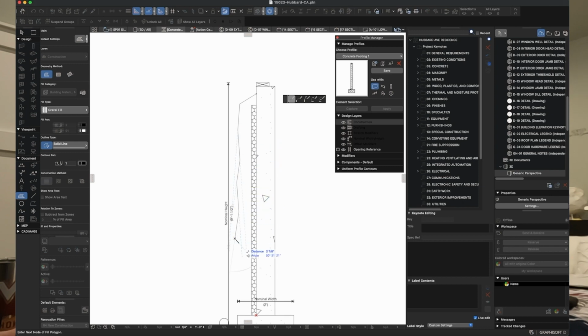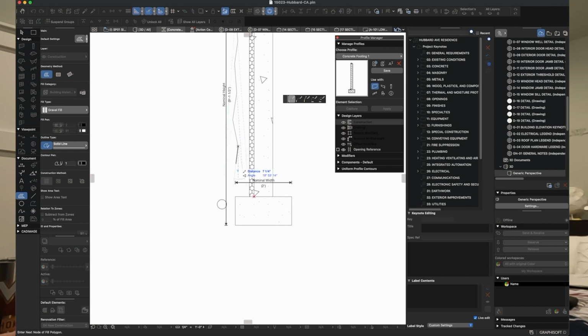The reason for it is a gravel chimney is basically up against soil. It's not actually going to have straight lines. So a lot of times I like to draw it a little bit wiggly so it's clear that it's more of a natural finish. And in this case, I'm just going to draw it all the way up to the top of the footing, assuming that there's going to be a concrete slab for the basement right over top of this. And let's close this off.